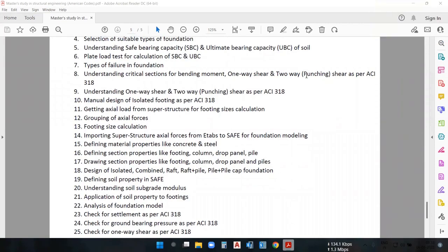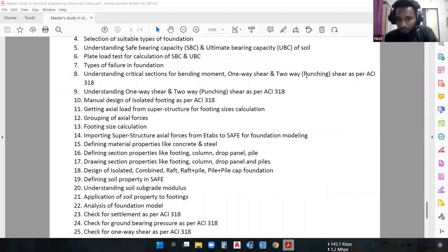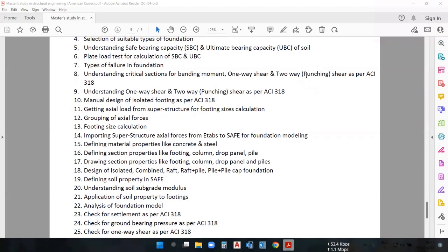While applying the wind conditions, how do you apply the gust factor? It basically depends on whether the building is a flexible building or a rigid building. If the building is flexible, only in that case you have to consider a different gust factor. If it's a rigid building, then the gust factor will be 0.85. It is standard, 0.85, if the building is rigid. And a building is called rigid when it has a frequency less than 1 hertz.